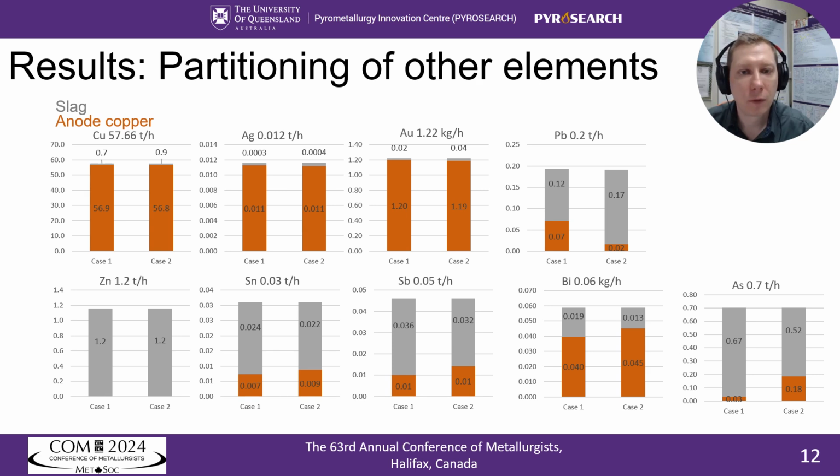The recovery of copper, silver, and gold is very close for cases 1 and 2 and can be considered the same within the accuracy of non-thermodynamic parameters. It is largely determined by the efficiency of the slag crushing and flotation stage, which is not very well studied quantitatively. A reasonably large difference is observed for lead, and it can also be explained by the difference in the distribution coefficients at the converting stage. Opposite to arsenic, calcium ferrite slags are worse than iron silicate slags for lead removal.